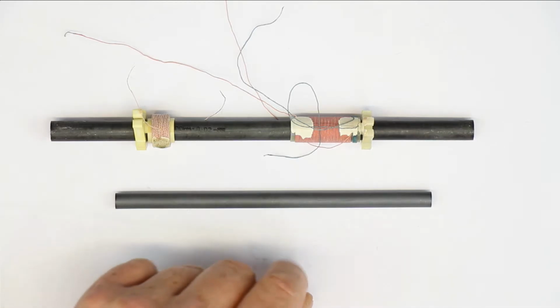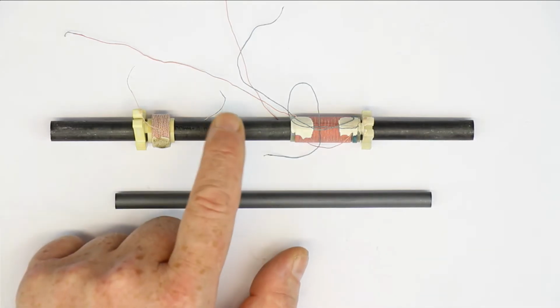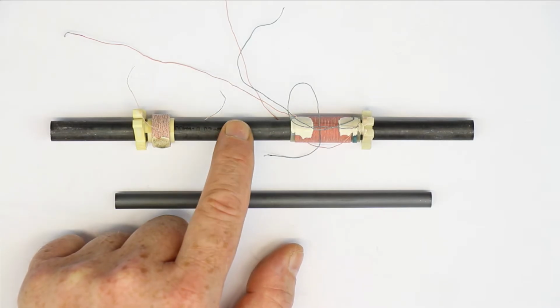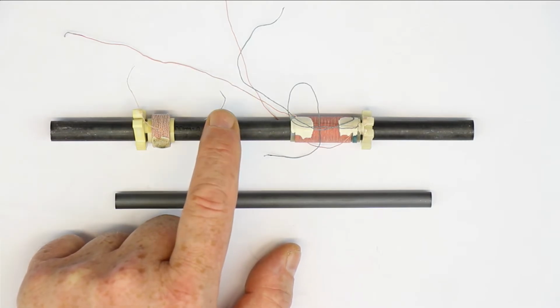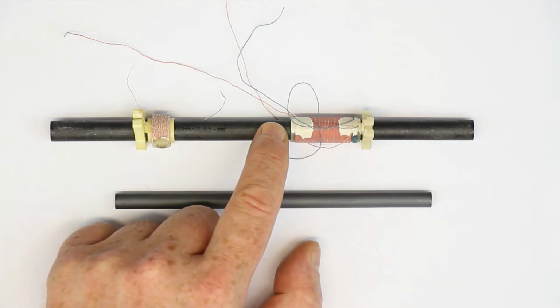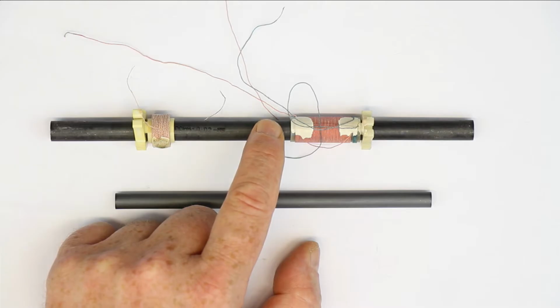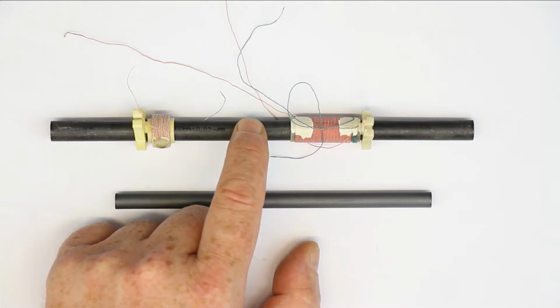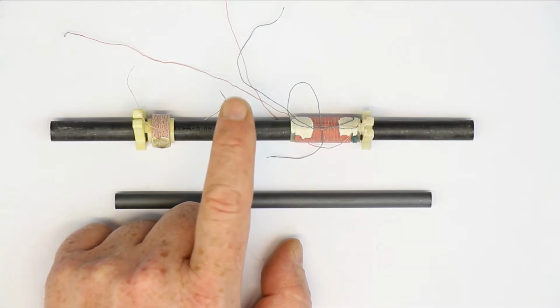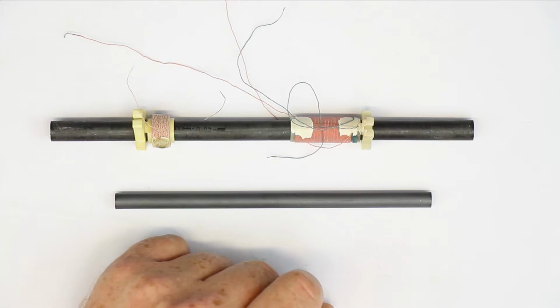And to get away with either a very large diameter of your coil or many hundreds or even thousands of windings or turns, the idea is to use a ferrite material, because you can imagine that it amplifies the inductance of a coil with a factor that is called mu-r, the relative permeability of the ferrite material.